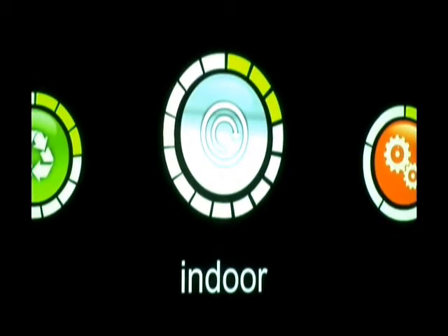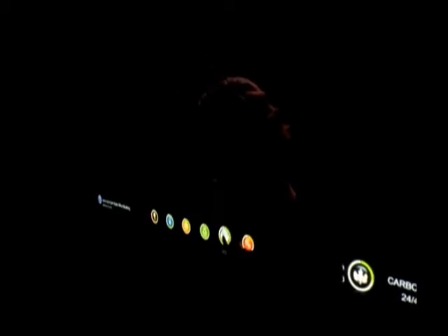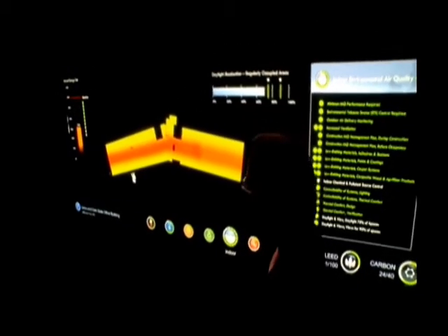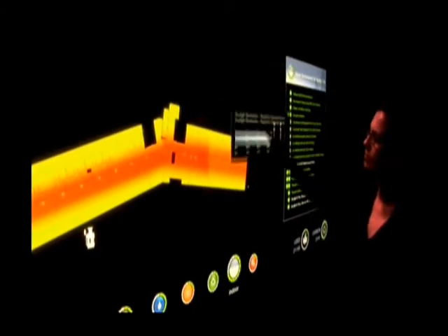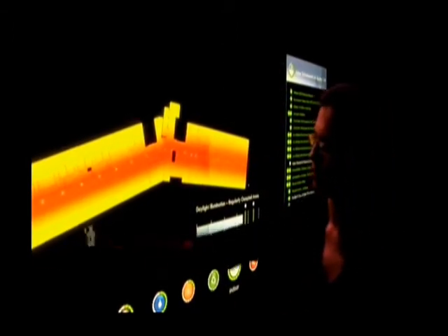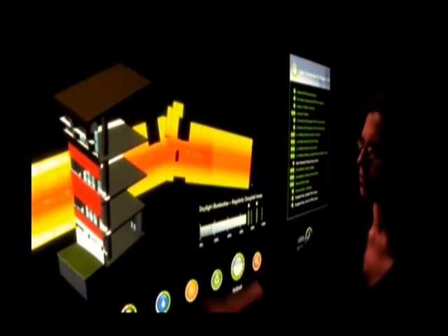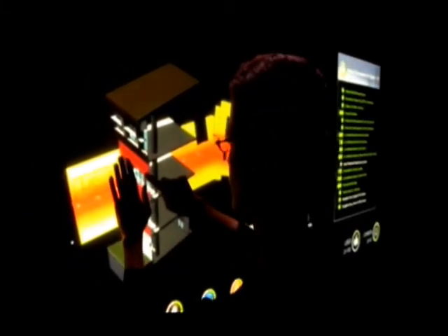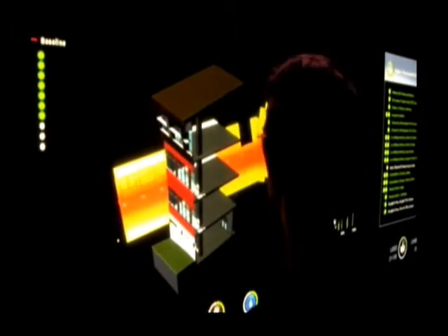Indoor environmental quality. With the model more developed, additional analysis can be performed and acted upon. In this scenario, the daylight analysis view shows that the project hasn't achieved daylighting LEED goals. Increasing the window height brings more light into the workspaces.